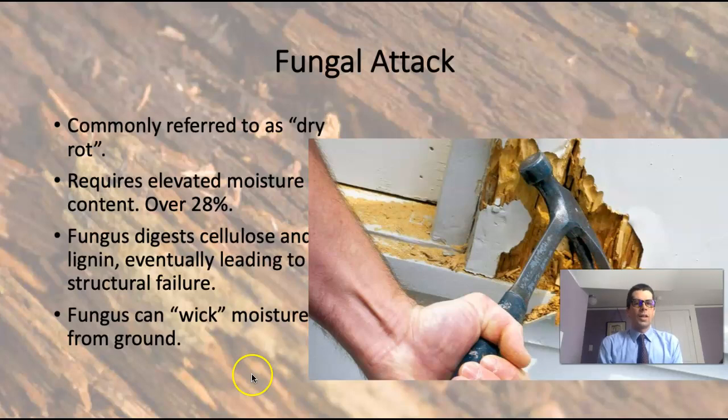I want to talk about why it's called dry rot, because it's kind of interesting. The fungus is present, okay? As soon as moisture conditions get to a certain point, it can start to decay the wood. And so shipbuilders actually noticed this phenomenon where they would be sailing out on the ocean, everything was great, and then as soon as they put the boat into dry dock, all of a sudden it would rot just instantly. Okay, so the fungus was present. When it was out in the water, there was an anaerobic condition occurring because it was totally saturated in water. As soon as they put it in dry dock, there was enough oxygen for the fungus to reactivate, and it could start decaying the wood.